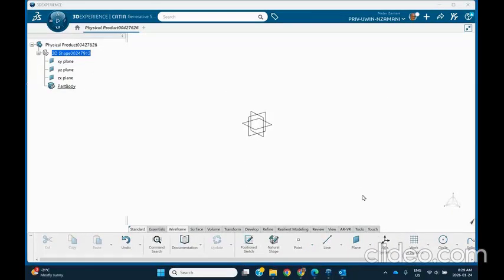All right, so let me go ahead here. I'm going to do this in the context of three profiles, three sections, and both a guide curve and a spine, where I use the Relimited on the first and last sections. First thing I'm going to do is to create two planes.